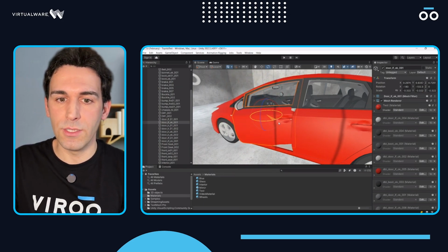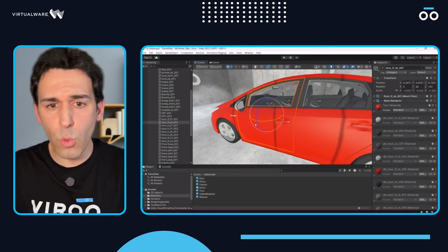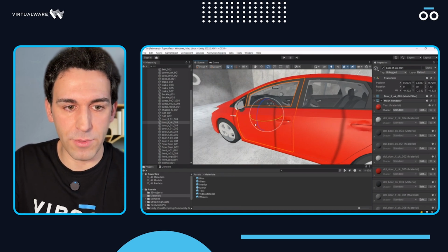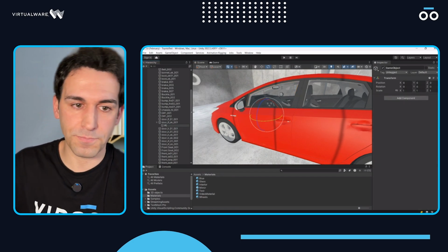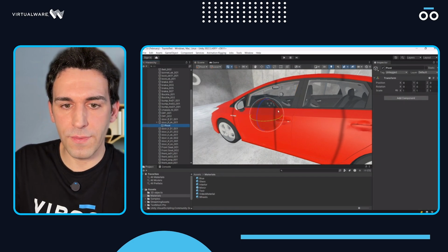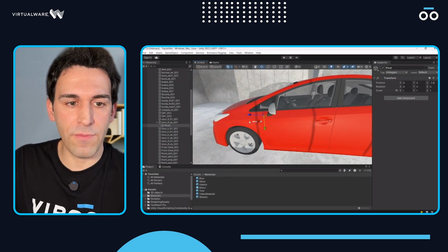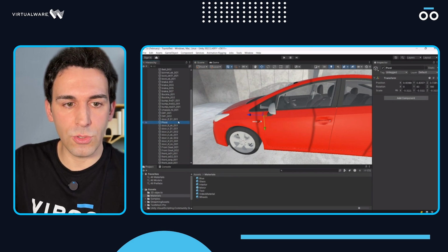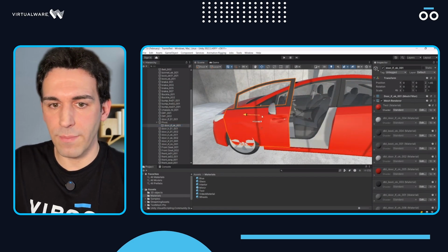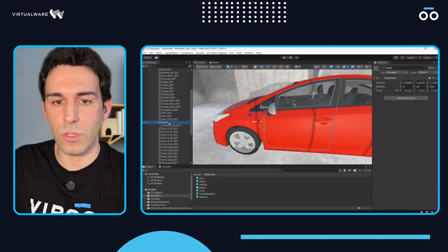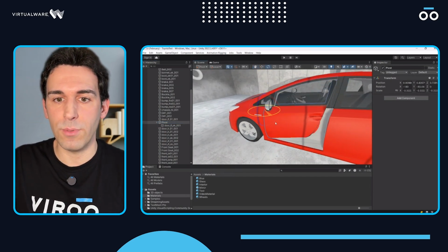This happens sometimes. Whenever we encounter this kind of problem, we developers here in Unity create an empty game object to use as a pivot point. Let me show you how that works. I'm going to create a game object here and call it pivot. Now I can move this invisible game object to the pivot point of the door. If I put the door as a child of that, whenever I move the door it's going to move normally. But if I rotate the pivot, it is going to behave exactly as I want. So now I virtually change the pivot of my 3D model.